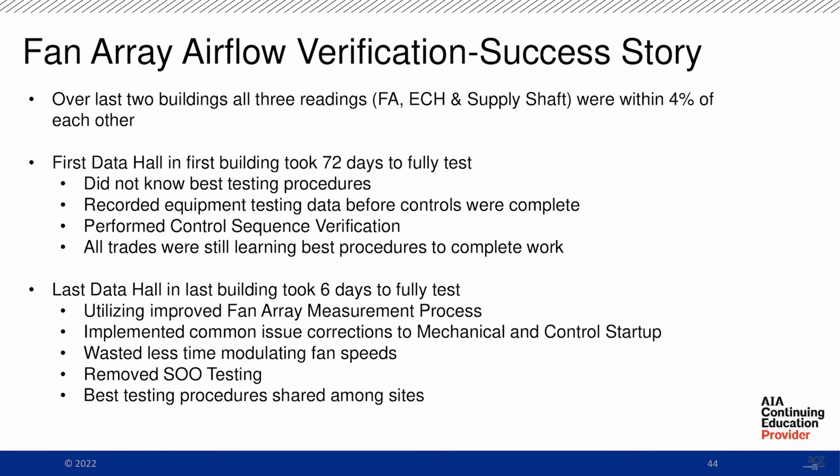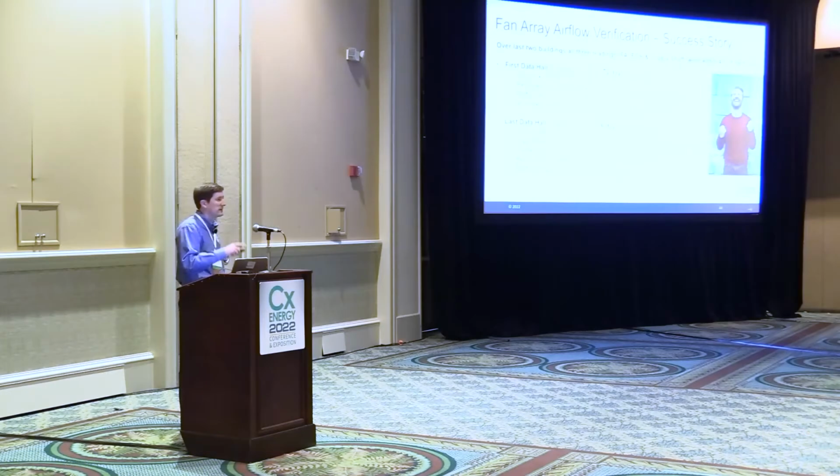We improved the fan array measurement process, implemented all the common issue corrections and mechanical control startup, and wasted less time modulating fan speeds. We just measured at 100%. We removed the SO testing, and then our testing procedures were shared among all the other sites.